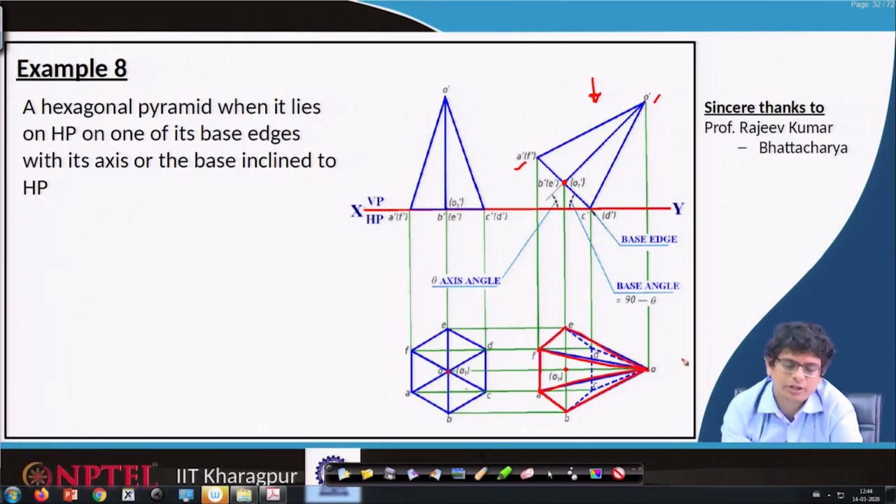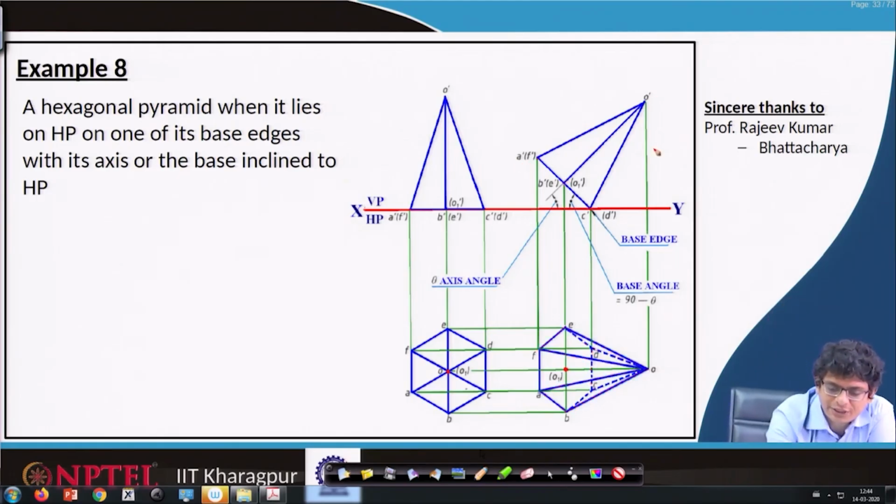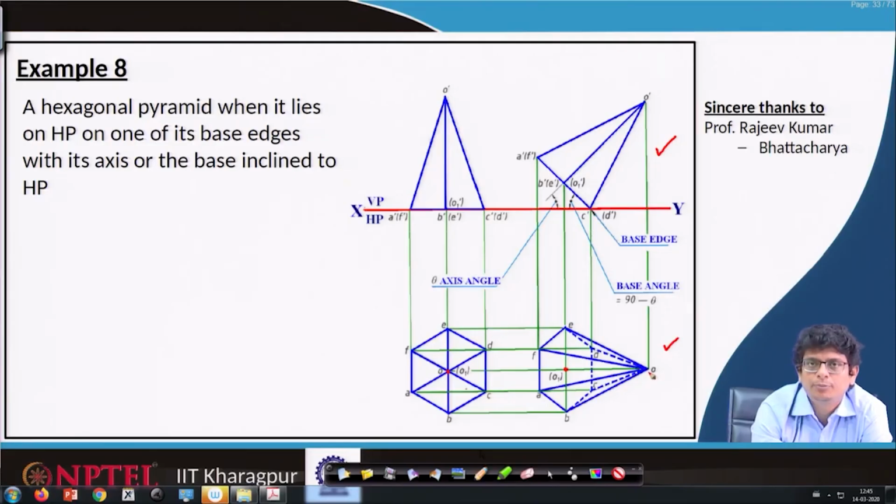So, this is the way the pyramid really looks, and the other internal things at the back side are not visible. So, it goes in that way, and this C to D line is also invisible. So, we will have that dashed line. The overall construction gives us the front view looking like an inclined one, and the top view makes this obscured kind of pyramid.